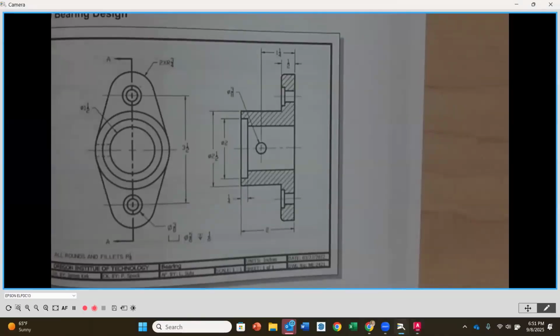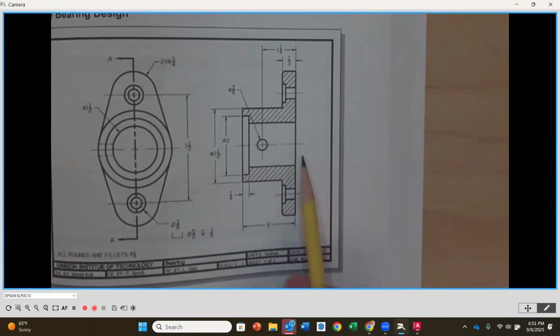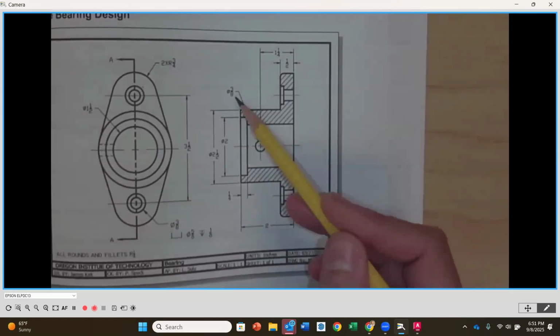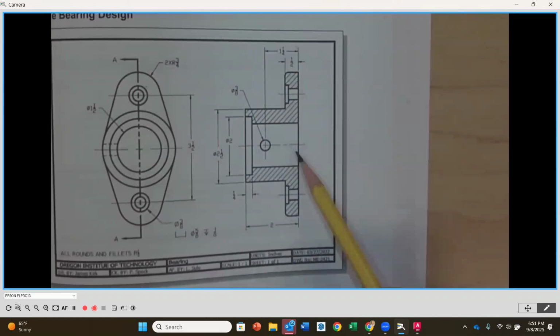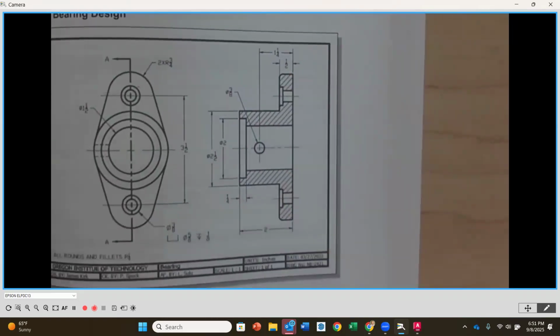Okay, so then now let's go back over here. Let's see what we got underneath. So we have created this area here. Let's put that hole in there since we're in that particular area. So to put this hole in, this is a diameter of 3/8 of an inch. And from the bottom on center, this is 1.5 inches.